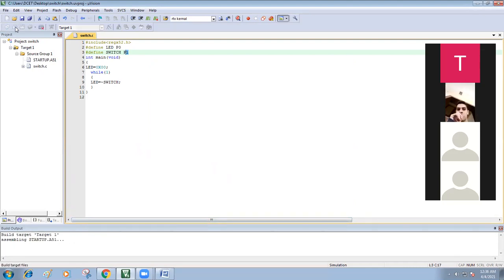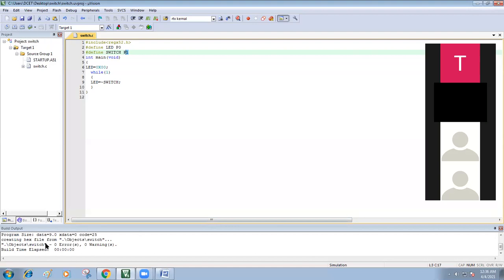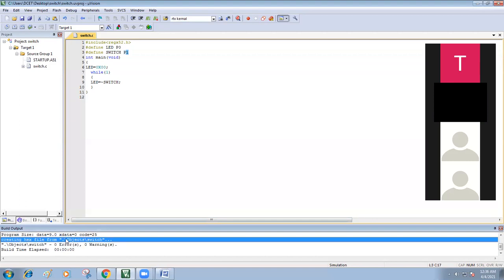Okay, next rebuild this one. So here you are getting a hex file to be created. You can see here the creating of the hex file. By using this, whatever application you have run in the first compiler will be converted into a hex file. Next, in the third compiler, rebuilding it, you are linking that file.